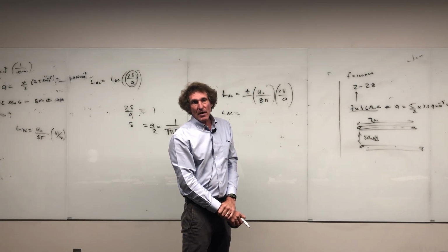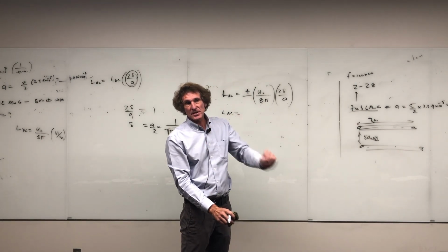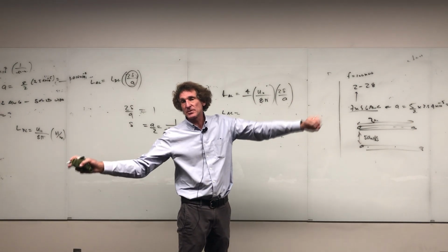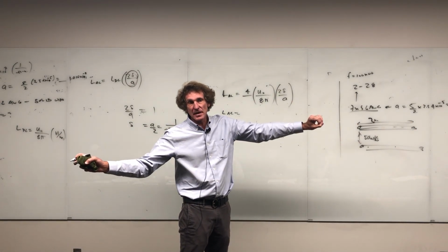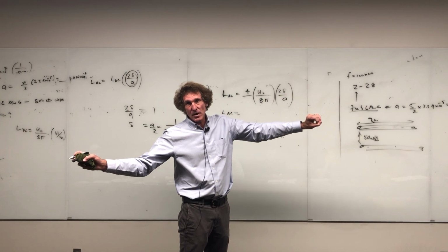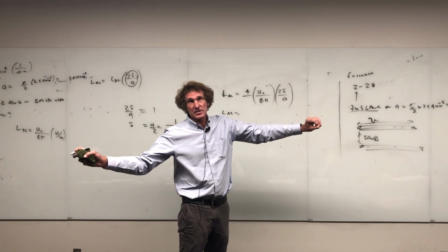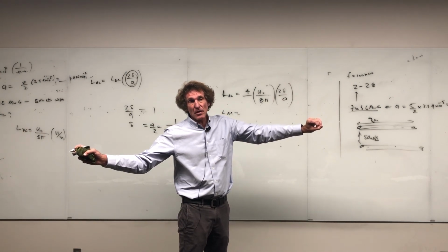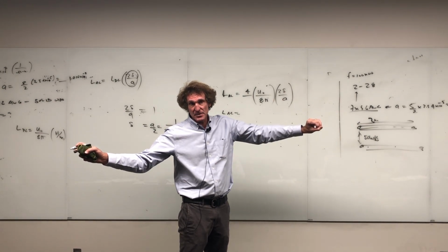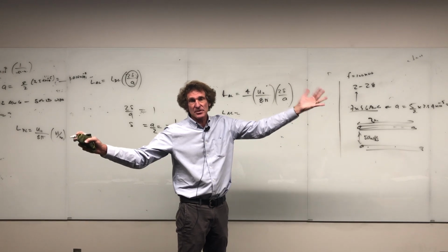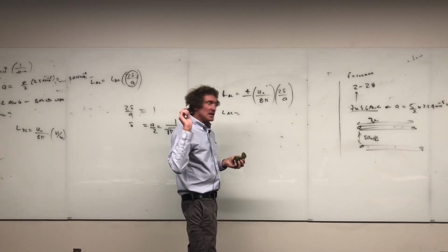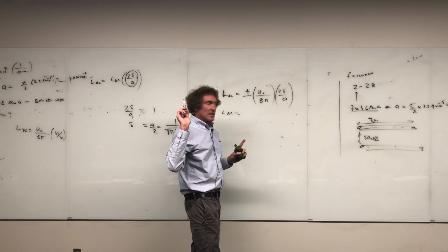When you're running wire harnesses, if you're getting signaling from experimental measurements to something that's going to collect the data, and it's not fiber optic, depending on the frequency, at clock cycle frequencies, you can all of a sudden have a line where the AC resistance is huge, and it becomes the limiting factor, and you're just getting partial data samples. Fiber optic is the way to go if you do measurements.